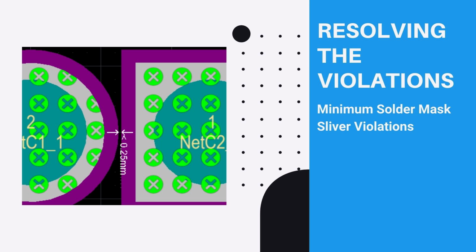However, a simple double-sided board like the board in this tutorial is more likely to be fabricated as a low-cost product, requiring a low-cost solder mask technology to be used. That means resolving the solder mask sliver errors by reducing the solder mask expansion for the entire board is not an appropriate solution. Like many aspects of PCB design, the solution lies in making thoughtful trade-offs in a focused way to minimize their impact.